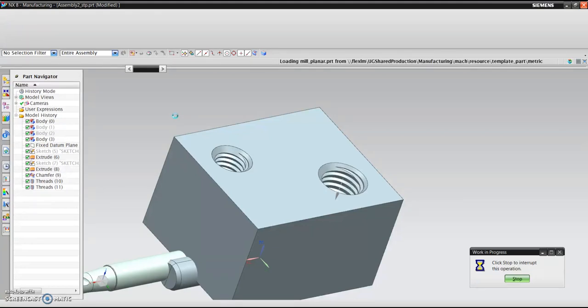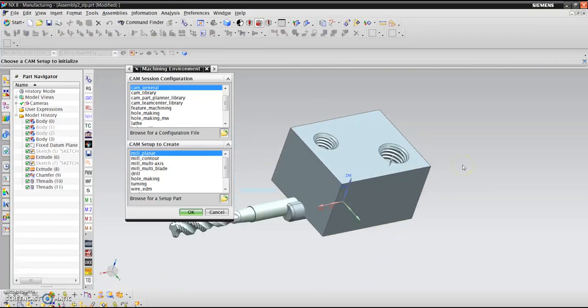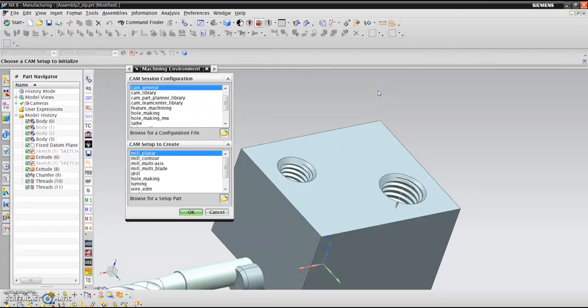For all hole applications, the number one criterion is to check the length by diameter ratio of the hole that you're trying to make. As long as the length by diameter ratio is less than 3, that calls for a really fantastic, robust manufacturing part. The reason is that now you can use the stubby drill, and the overhang from the spindle to the cutting zone itself will be much less. So everything will be a highly rigid process.